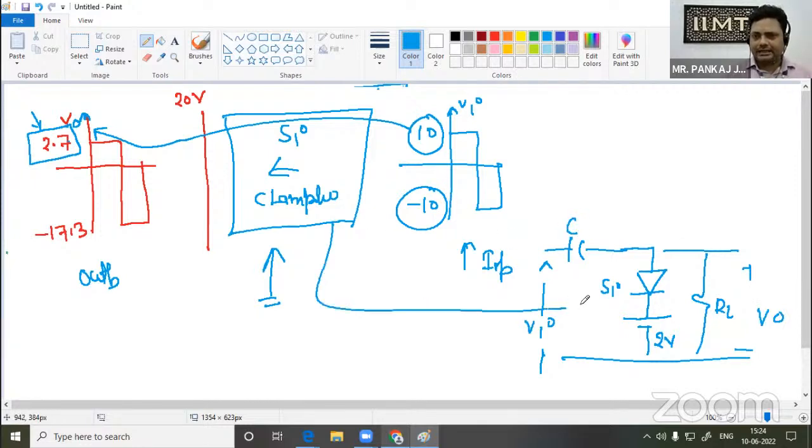After designing this circuit, if you have gone through all the lectures and listened carefully, obviously in the positive half cycle for this circuit we will get 2.7 volt output, which is our output, and in the negative half cycle by solving we can get 17.3 volt. So by concentrating on the lower value, we can easily draw the circuit of the clamper. I will take one more example.